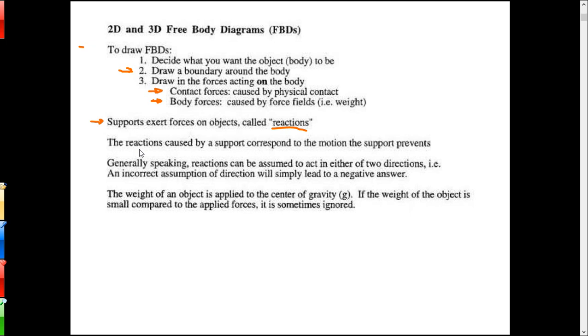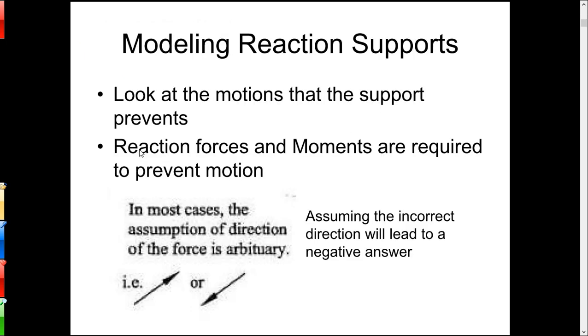So when you're looking at how to model these different supports, you look at the motions they prevent and then replace them with forces and perhaps moments. Okay, so reaction forces and moments are required to prevent motion. That's how you look at that.